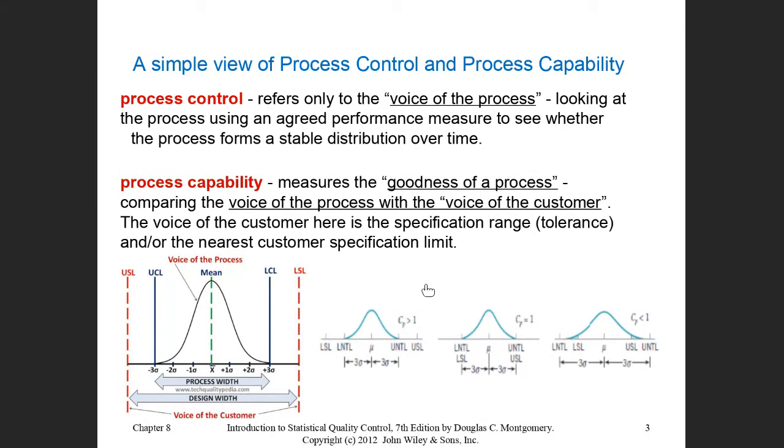If you are going to do the control chart and you are not meeting your specifications, what is the point then? You will measure a variation and you may see the process is in control, as you can see on the right side of this picture. But every time, this side here in the normal distribution and the other side are exceeding the specification. That means the level of goodness of your process is not meeting the expectation.